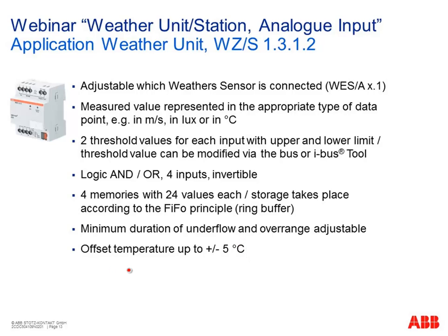Yeah, and we can also adjust an offset for our temperature sensor. Remember, it's an outdoor sensor or weather sensor installed normally maybe on the roof of the building, so not on the earth directly. And maybe the temperature measurement is not that precise for the temperature on the ground, so we can adapt it a bit by such an offset here.